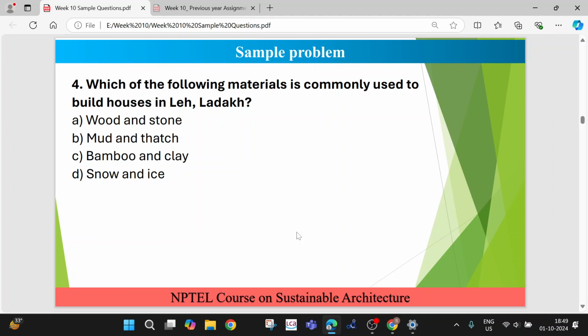If you are talking about warm and humid climate conditions that prevail in Assam, or where there is heavy rainfall, then in that region, without any doubt, you can say a pitched or inclined roof will be very, very good, because whatever water comes will easily get out.